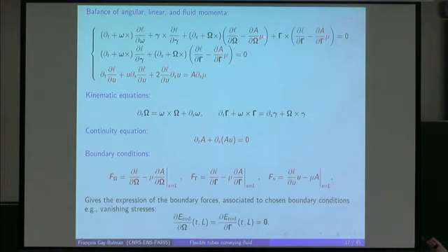You have some formula for the area. The way it depends on omega is multiplied by the pressure of the fluid, and this is what really acts on the tube equations. Is the area constrained to be circular? No. Not here, but for our concrete calculations, yes. But no, this works for any kind of area.